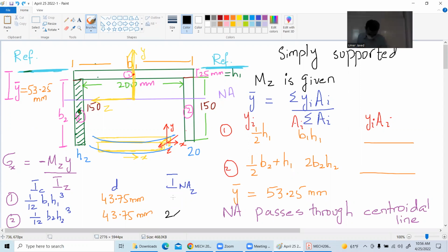It's confusing. Sir, can I ask something? What does D stand for? Parallel axis theorem. The distance, I just said, the distance of this rectangle's centroidal line to the centroidal line of the whole structure, of the whole cross section, which is this line. So this little thing is the D. Okay, what is the D for this rectangle? You can help me. It will be the distance of its own centroidal line to this line, the purple line.